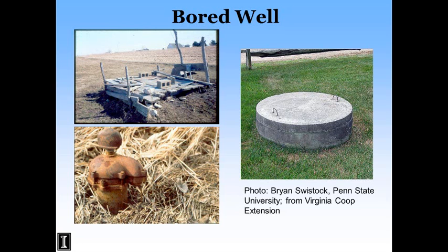This is an example of a hand dug well that has been here since the 30s. There's the electric outlet for it. There's a water line that runs back to the house. This is a cattle pasture. This is a cornfield. And they've got boards and tin with cement blocks on top of it to protect it at the surface. There's insect issues. There's runoff issues if there were a huge rainfall event.